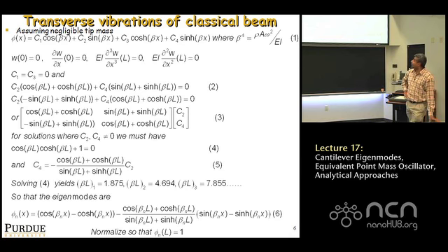So now we're left to determine what the constants C2 and C4 are, for which we go to the latter two boundary conditions. We put in those expressions at x equal to L, and we rearrange. We're trying to determine C2 and C4, and effectively what we get is equation 3. The right-hand side is missing. It should be equal to 0, okay? So really what you have is this matrix times C2, C4 equals 0. And we've got two equations. We're trying to solve for C2 and C4.